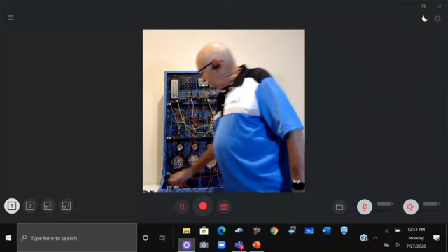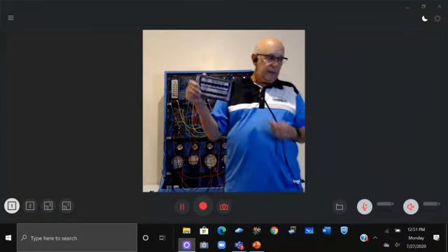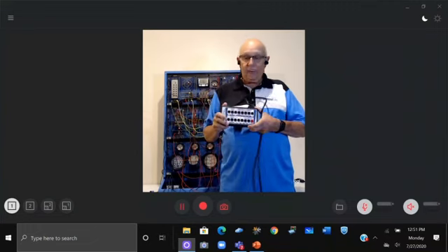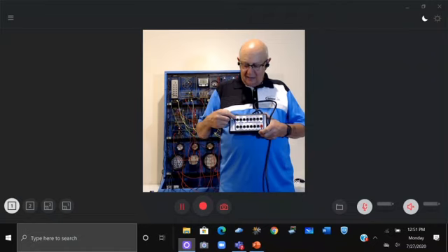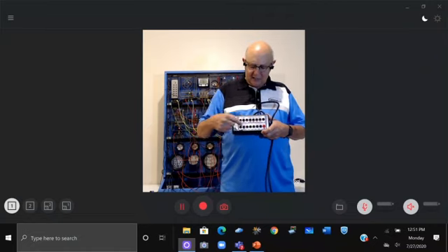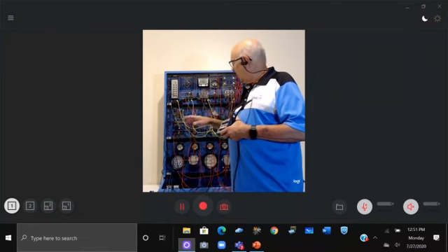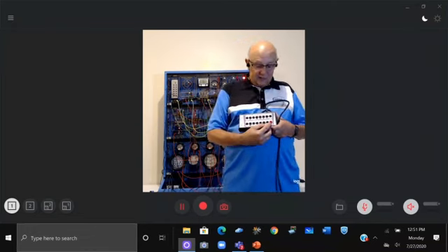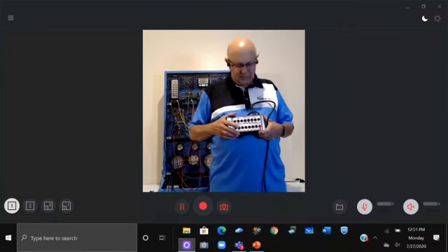Before I do, one of the things we're going to get into is a breakout box. Now, I'm not selling any particular breakout box, but a couple things about them. I think if you get a breakout box, get one that's got some lights on it. There's nothing better than to be able to look at the DLC through a breakout box and see a power light on and see the two ground lights on. It just makes a lot of sense.